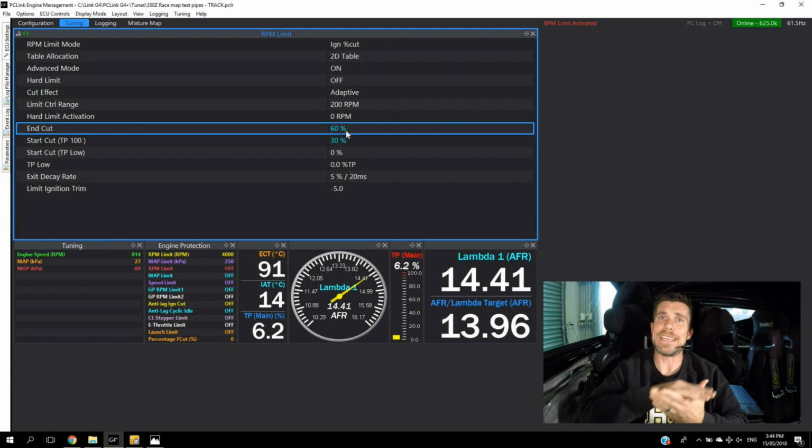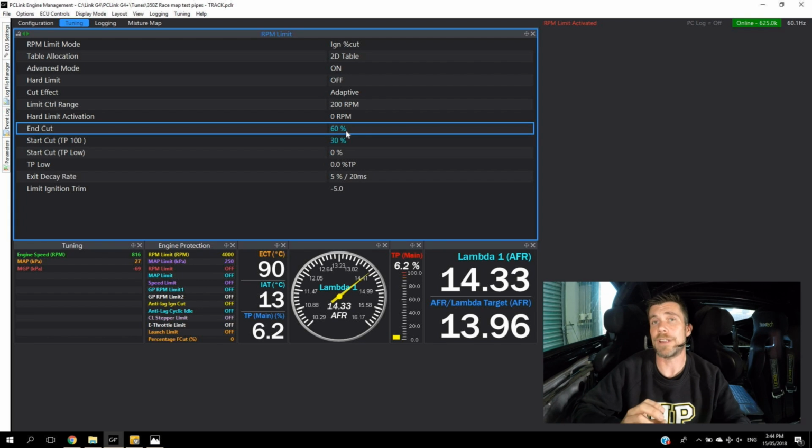What we're trying to do is get a perfectly flat RPM line on our limiter and control our RPM very, very accurately. If we're seeing a 200 RPM change on our limiter, then the difference between the driver dropping the clutch when the RPM is at the peak of that 200 RPM range versus when it's at the trough is actually a significant effect on our engine power, and it's really, really hard to get consistent starts or consistent launches when that is the case.